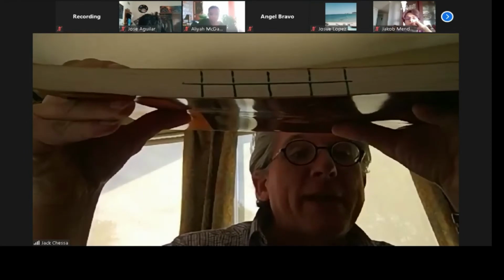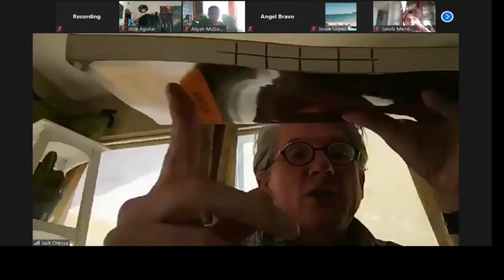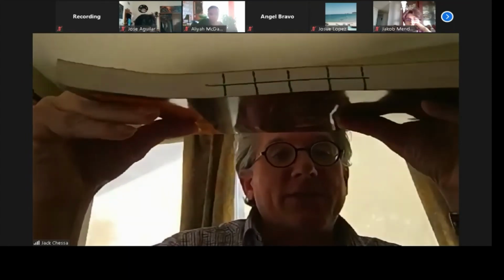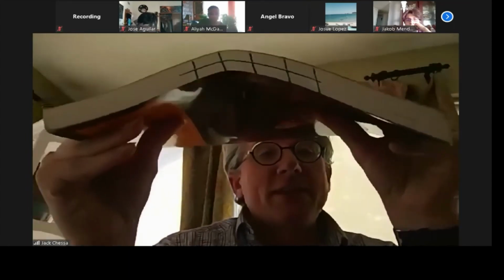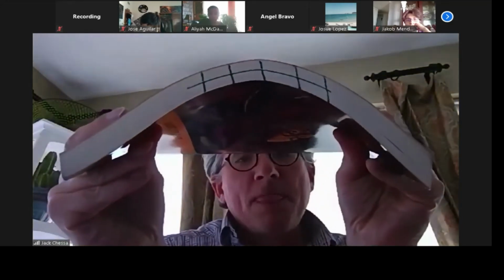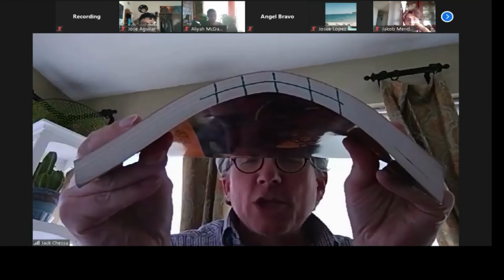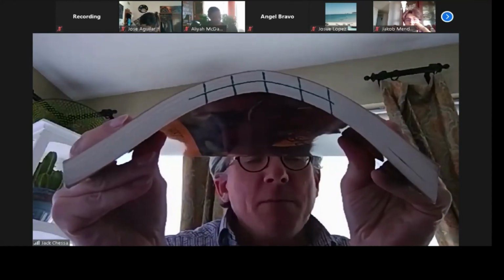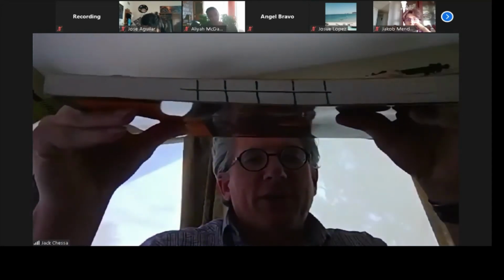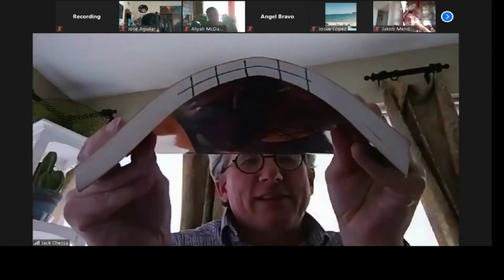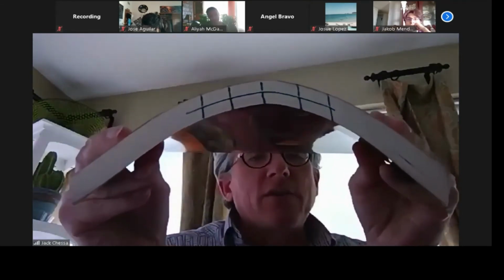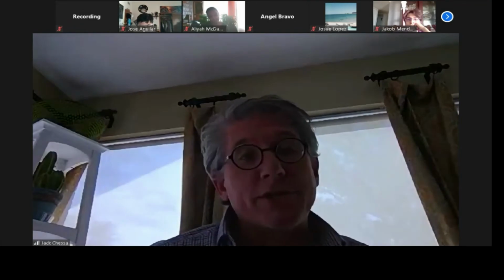Imagine this is now a beam. So we have the cross sections, and I also have drawn what would be the neutral axis. Now, if I bend this, you can see obviously that those cross sections do not stay perpendicular to the neutral axis. They actually almost stay vertical, which is definitely different than what we talked about for our beam bending assumption in chapter 6.